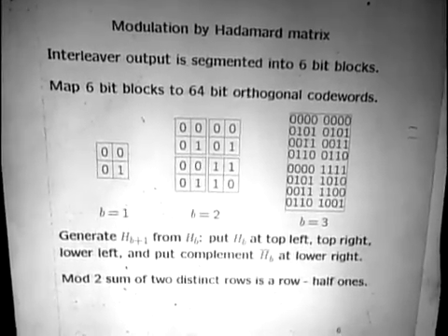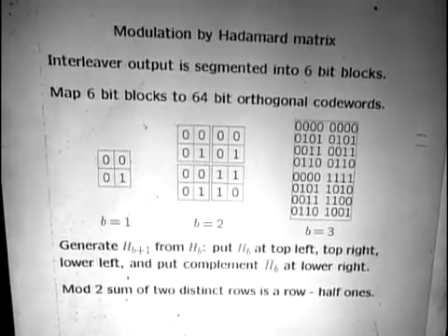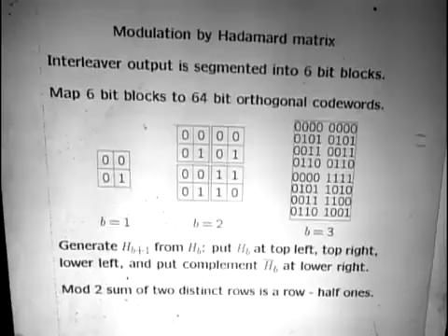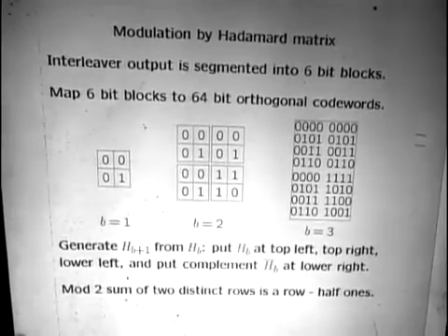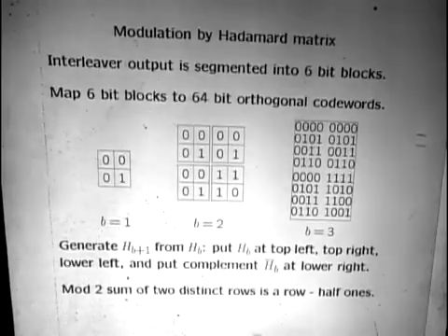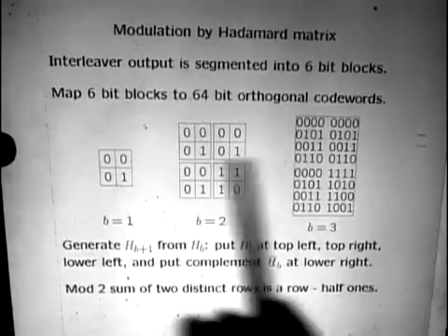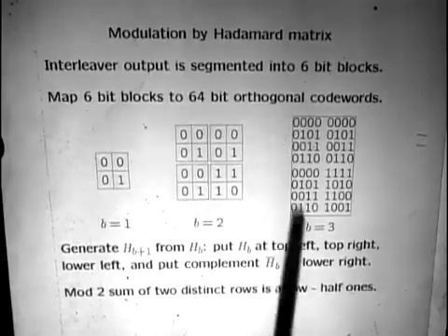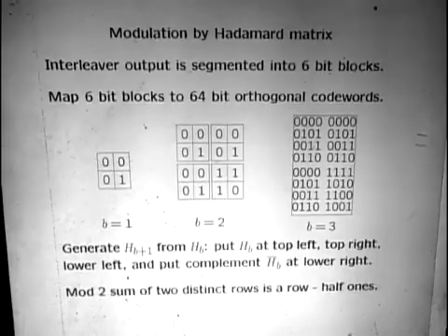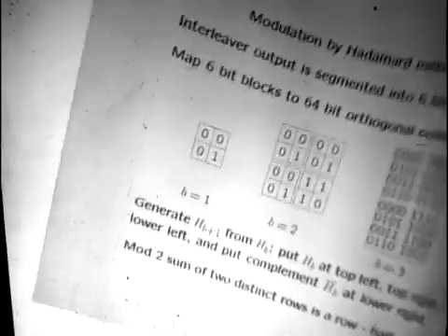Why do we want to use this orthogonal code rather than just an orthogonal code which uses the first degree of freedom and sends an enormous amount of energy, where the second degree of freedom sends an enormous amount of energy, and so forth? It's the same thing we were talking about last time with regard to channel measurement. You don't want to send enormous amounts of energy in any one degree of freedom. You want to spread it out over all of the degrees of freedom, and that's what all these codes are doing. All these codes are using 2PAM on each degree of freedom to generate a code word, so the code words all have sort of uniform power in them.